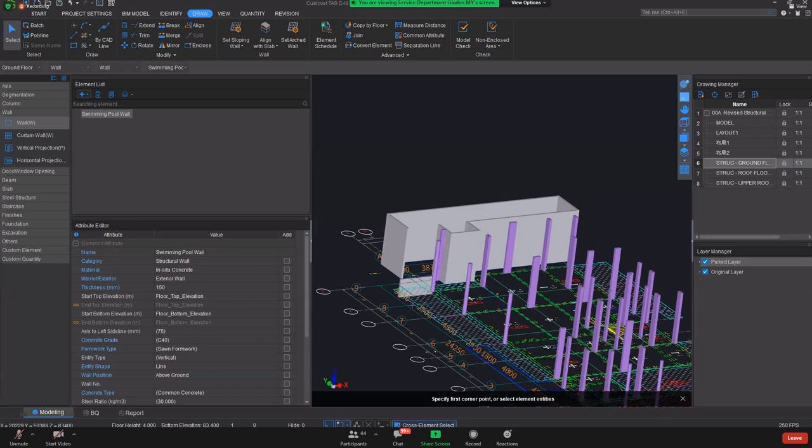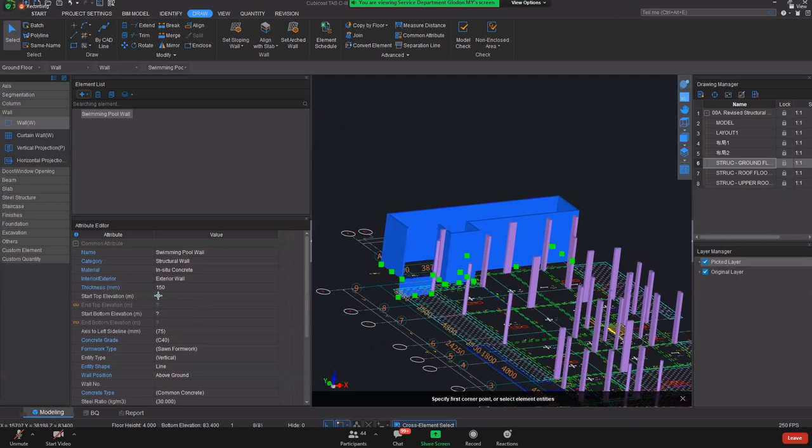So now you will ask me again, hey, Sam, why is there a question mark here? The question mark here actually indicates the uneven value of the elevations between all these walls, because I already changed this particular wall. So it will be uneven, and it will read as question marks. If I just left click and deselect this wall, it will go back to this. It will be a very uniform elevation for the remaining walls.